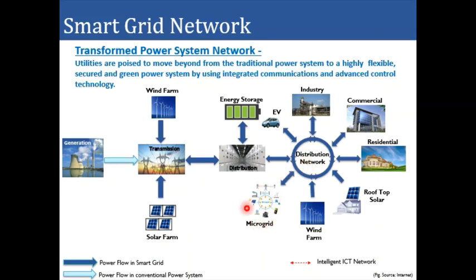So intermittency of the supply and the load will cause challenge in the distribution network. Also, the distribution systems are now being integrated with large energy storage systems, which we generally call grid connected energy systems. These are used for various functions such as demand response management or frequency regulation. So these are also generators as well as loads for the distribution system.